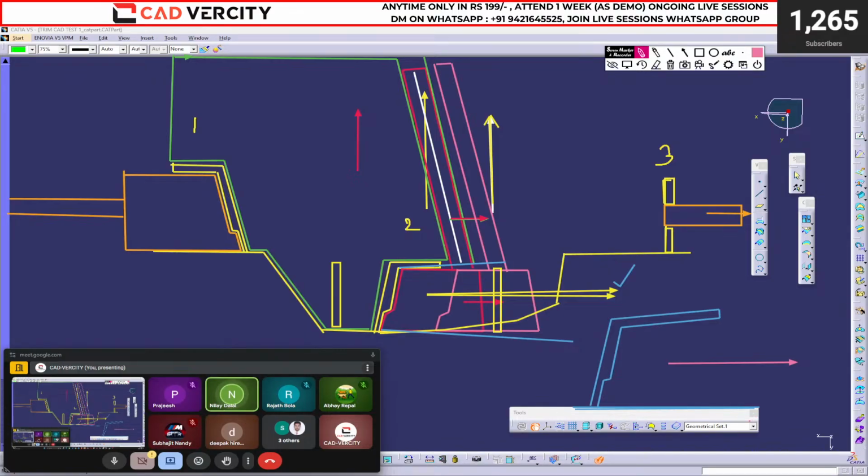On the bottom surface, there is no draft. Because of that, the slide will be a parallel slide, and it can create scratches on the surface. That's why, remember what we did over here? We will lift the lifter direction by hardly 0.5 or 1 degree, on the safe side. So instead of using this lifter, we will use this one.